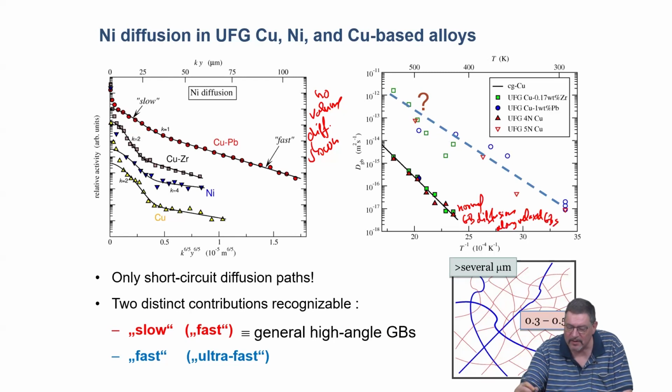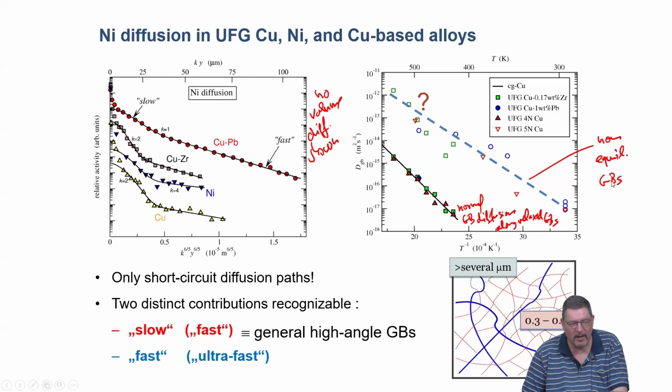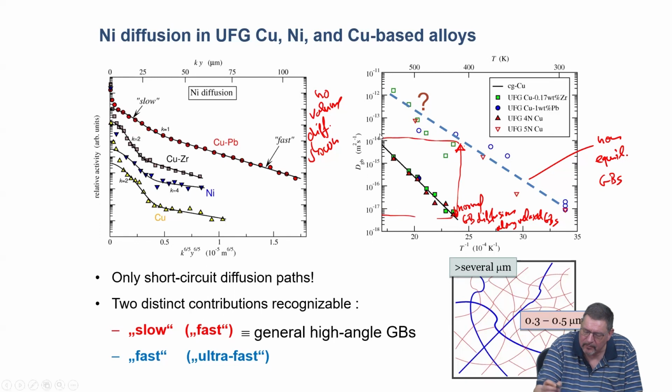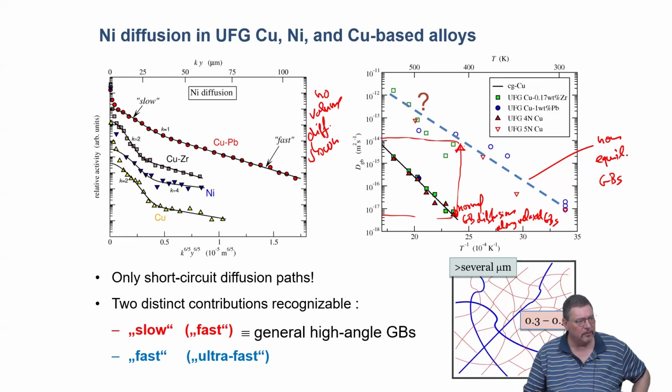Along relaxed grain boundaries, and this is for the non-equilibrium grain boundaries. If you now compare it at constant temperature, right? So you compare maybe here, then you see, whoops, almost 4 orders of magnitude difference. If you extrapolate to lower temperature, it might be 5 or 6 orders of magnitude. So this is a huge change in grain boundary diffusivity. Actually, it's so huge that the mechanism needs to change in order to explain it.